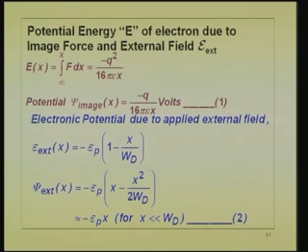The potential due to that is the integral of that, and I am putting that minus sign to tell you that if you go this side, electrostatic potential goes up as x increases, but when you go towards that side, electronic potential decreases. Okay? That is how you draw the energy band diagram. So, that is why I put that minus sign there. Otherwise, when you integrate for electrostatic potential, the integral will be minus E peak into that. Anyway, we can very easily understand from physical terms that from x equals 0 on the right side, electrostatic potential becomes more and more positive, and electronic potential becomes negative, just opposite. Okay. Now, let us plot that.